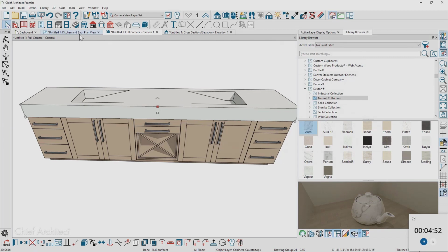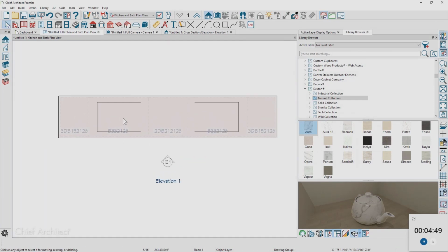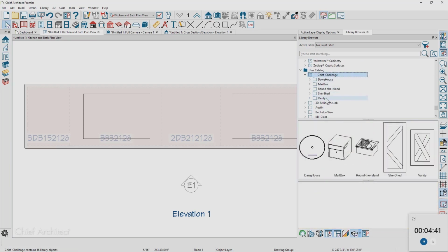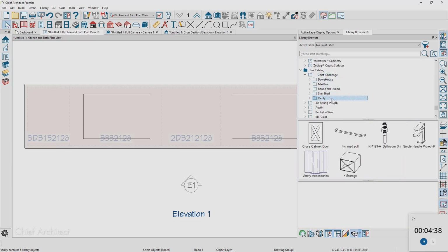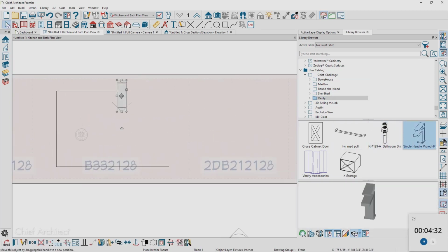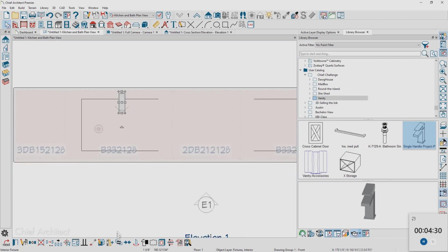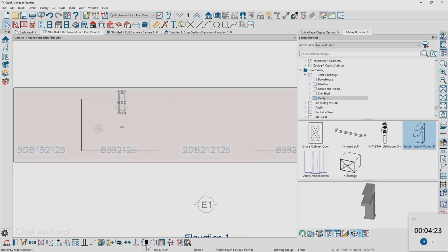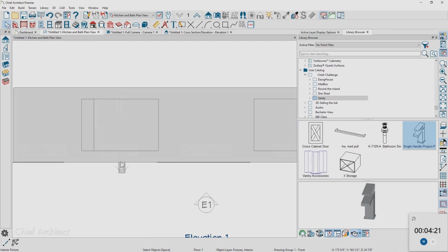And then as we come in here for the drain and the faucet, let's come back down into the Vanity dialog or catalog, and let's grab our drain and our faucet. Place those two items, and make sure that they're positioned approximately where we want. Let's go ahead and center that on that cabinet. So we'll use the center tool, pick the center up, and it's centered.